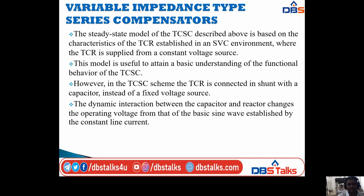Next, the steady state model of the TCSC described above is based on the characteristic of the TCR that is established in an STC environment, that is, the static compensator environment, as in the last chapter, where the TCR is separate from a constant voltage source. So this model is useful to attain a basic understanding of the functional behavior of the TCSC.